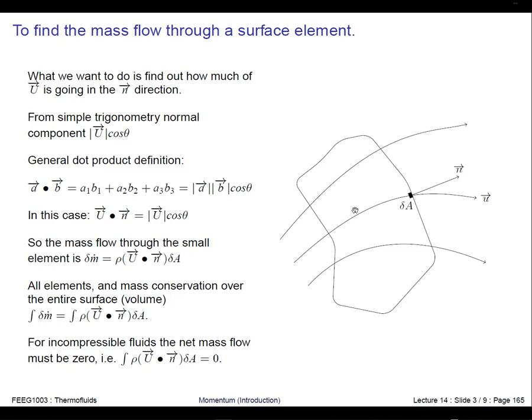So in this particular example, density is my stuff, my information that I'm transporting with my velocity field. Okay, and so when I write my conservation of mass equation, effectively I'm saying that the same amount of density is flowing into my control volume as is flowing out, and that must balance because it's a conservation of mass equation, so the sum of this particular integral must be equal to 0.